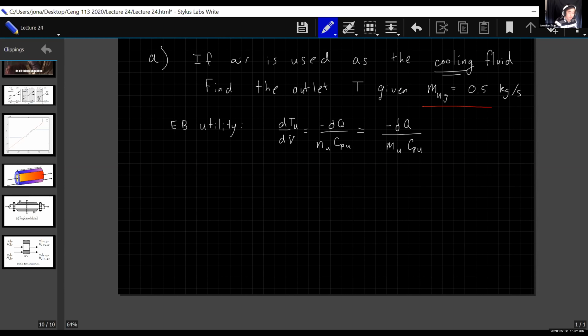And so the next thing, again, because we start with all of our material balance and energy balance, let's define the material balance for the PFR. In this case, it's going to be relatively simple. It's just going to be the expression that we have above, which is dXA/dV is equal to R divided by NA naught. I think the expression I actually have above is negative RA over NA naught, but we can express that as R over NA naught as well.